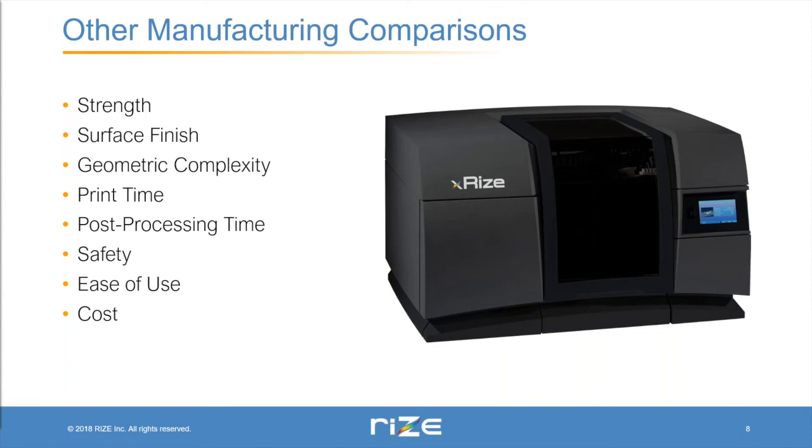Another thing is surface finish. So surface finish is in many cases closely tied to tolerance or resolution. So the resin printers are going to have very good surface finish. The powder bed fusion types of technologies are going to generally come in second, and fused filament fabrication usually has the lowest resolution, so it's going to have usually the lowest surface finish.